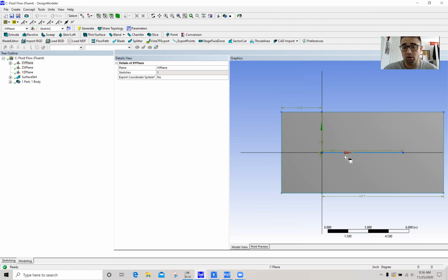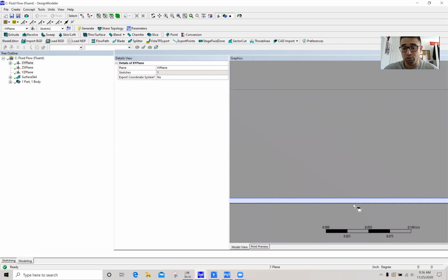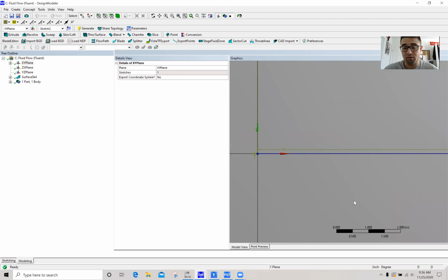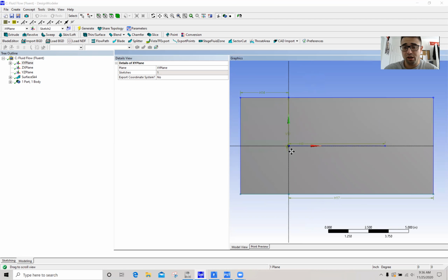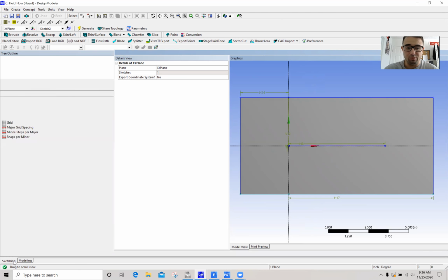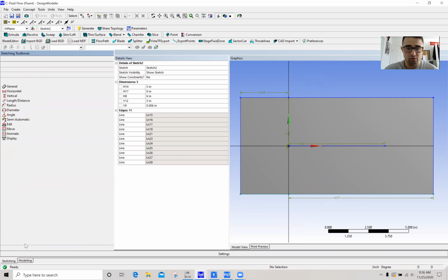So first and foremost, our plate here that we're going to be using is 0.06 inches in height and 6 inches in length in a test section that is 12 inches long and 6 inches tall. In order to create this overall geometry, my method was to first draw the plate as a tiny rectangle, then use the dimensions tab, which should be right here.